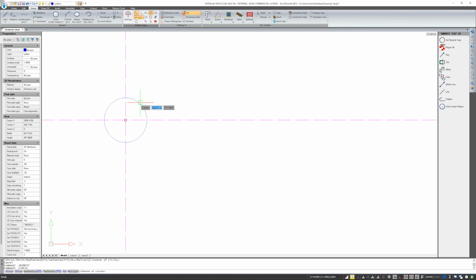But please note, if you started to draw a circle again, and I have turned off this nearest snap point, then without any problem, even without zooming in too closely to the drawing, this center point of the circle is very easy to snap to by the program. Thus, the arrangement of these snap points. It is good to check that there are not too many of these points, because then it is difficult to find the right one.